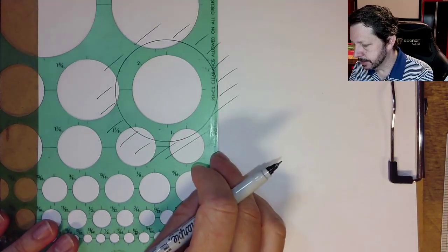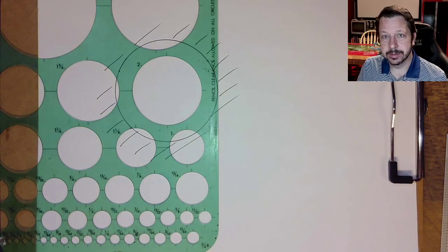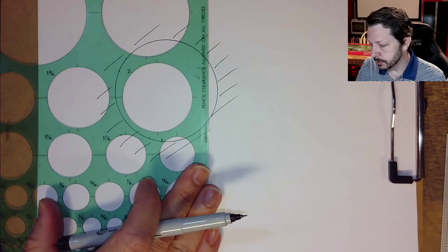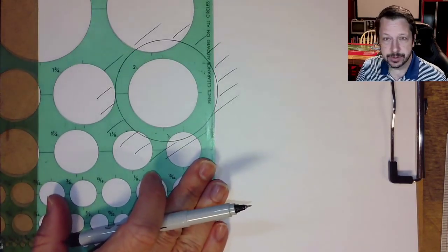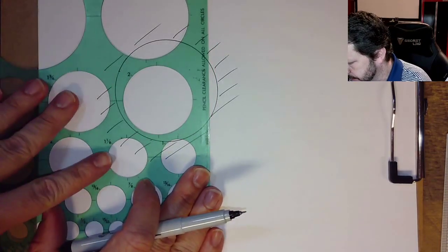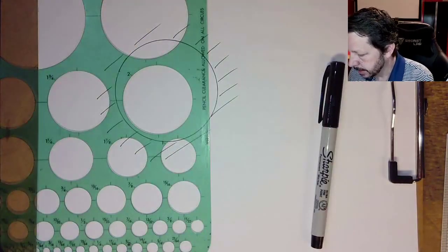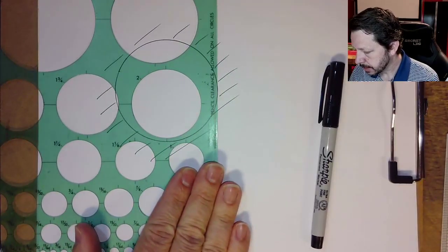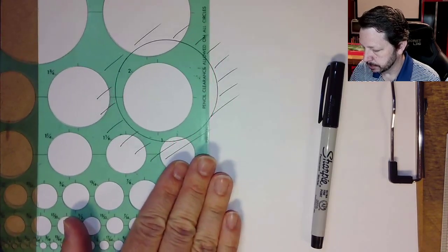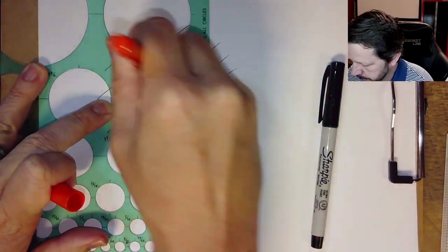Remember, it doesn't sit concentrically with that bushing, or it might sit there for a little while, but when it's in operation, it's going to move some. I'm going to exaggerate it. Normally you have super tiny clearances, but just so we can see things, I'm going to exaggerate it. So maybe our journal is over here, and it doesn't just drop straight down either. When it's spinning, the fact that it's spinning will pull it to one side, so it'll be something like this. So it's sitting over here.